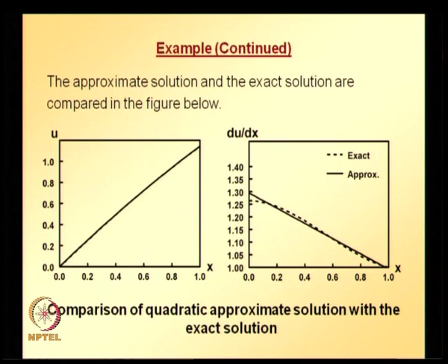Once you make an assumption of some approximate trial solution, make sure that it is admissible by making sure that it satisfies the essential boundary conditions, and then plug that admissible trial solution into the equivalent functional and apply the stationarity condition to get the unknown coefficients, solving the simultaneous equations that you get.